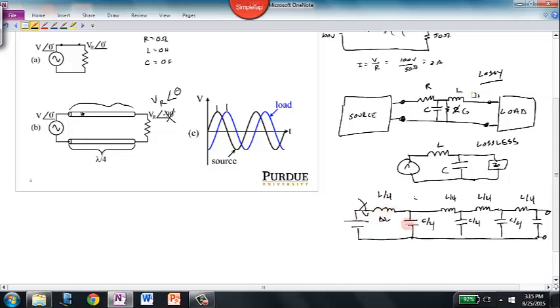As the voltage on this capacitor starts to climb, some of the charge is going to trickle into the second stage here. This process is going to continue until each of the capacitors is fully charged to the battery voltage, right here. Only after each of the capacitors is fully charged is the voltage of the battery going to appear across the load terminals. Only then will the load resistance see the full battery voltage.